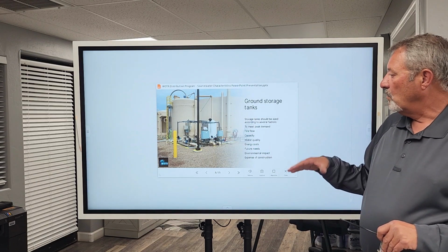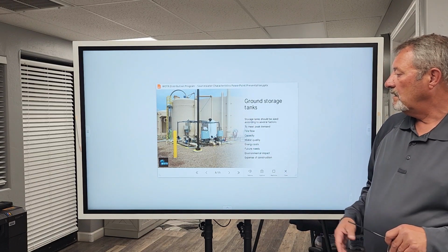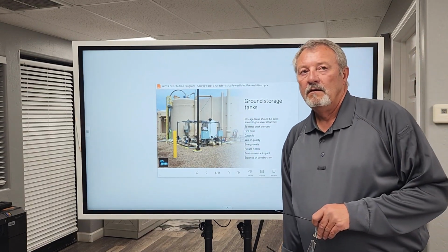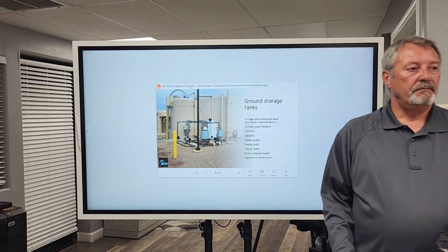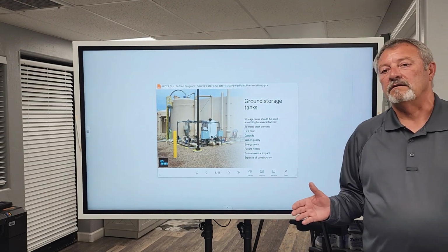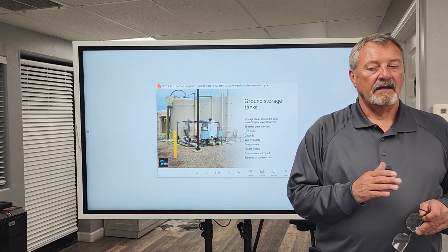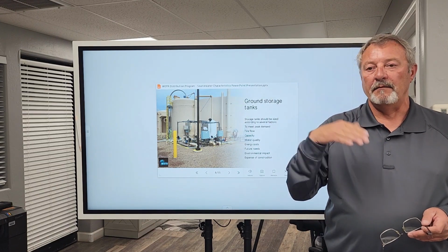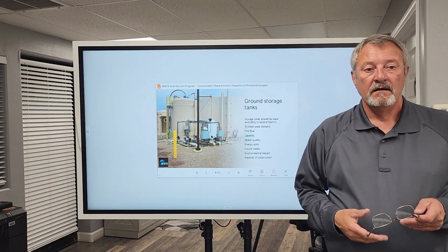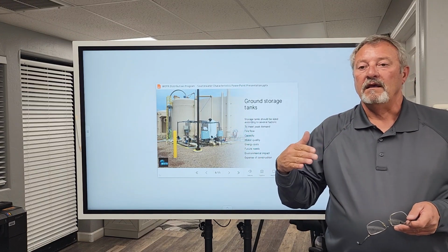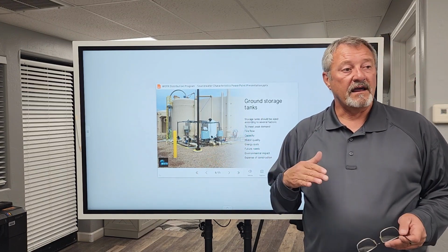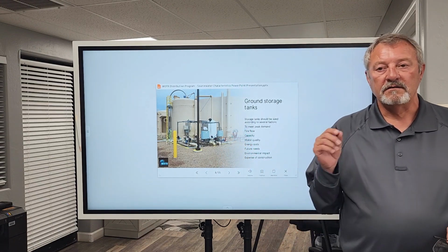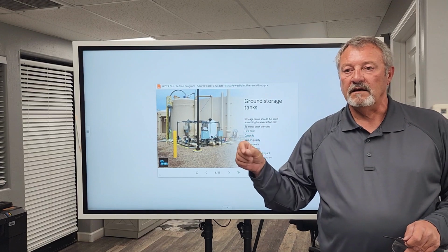So they're sized according to several factors. One is to meet peak demand. So what's peak demand? Well, if we deliver 1 million gallons a day to our customers, and we know it's 1 million gallons a day, what we do is divide that by how many minutes are in a day to get how many gallons per minute we're delivering to our customers on average through a 24-hour period. Well, through that 24-hour period, the water's just not being used at a constant rate. It varies.